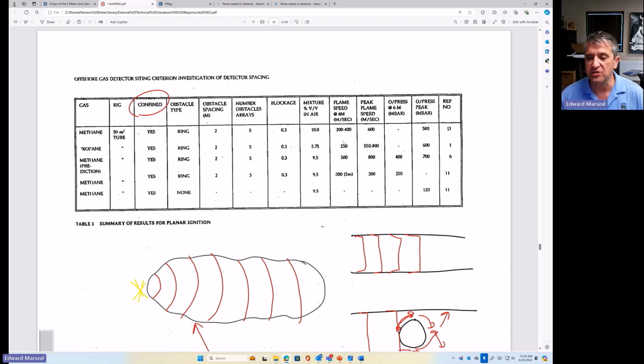Weather conditions have no impact. So when you're doing geographic coverage, it's easy, it's simple, you can do it fast because you're ignoring everything about wind speed, wind direction, locations of obstructions. All that is completely ignored when you're determining a critical gas cloud size.